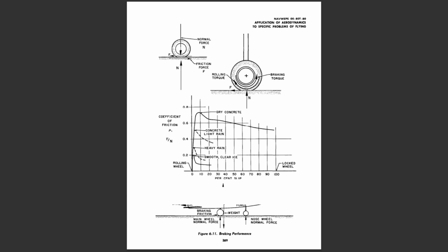When the tire is rolling along the runway without the use of brakes, the friction force resulting is simple rolling resistance. The coefficient of rolling friction is of an approximate magnitude of 0.015 to 0.030 for a dry, hard runway surface. The application of brakes supplies a torque to the wheel, which tends to retard wheel rotation. The initial application of brakes creates a braking torque, but the initial retarding torque is balanced by the increase in friction force, which produces a driving or rolling torque.